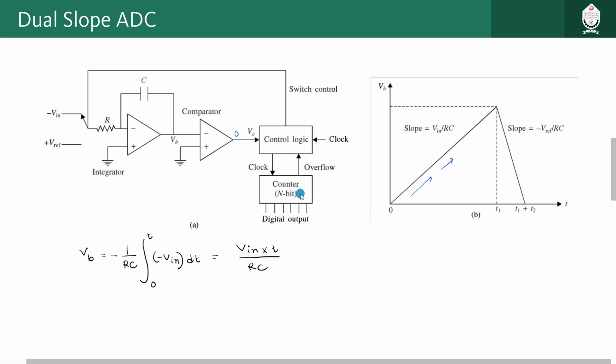So after each clock pulse, counter will increment its value, and this will continue, right, up to which moment? That is the question. It will keep continuing until it reaches its maximum value. If, as I said earlier, the counter is 3-bit, that means 111 is the maximum value it can count up to.